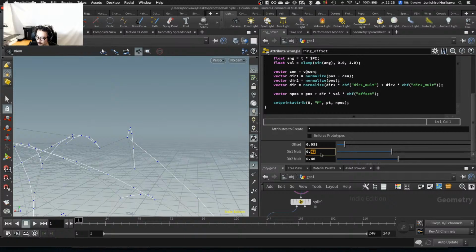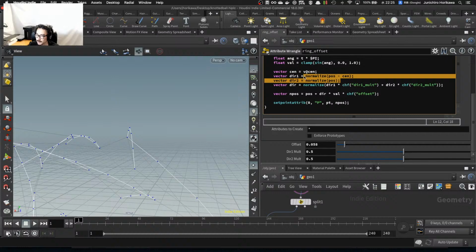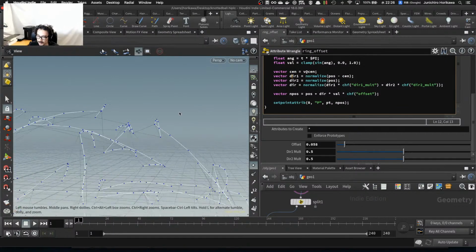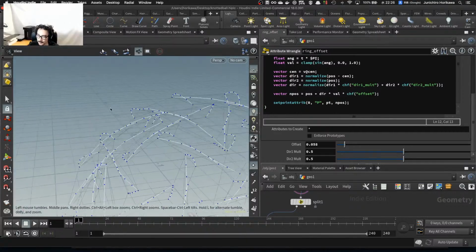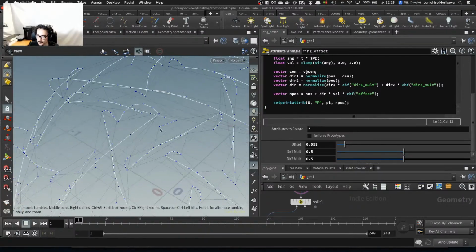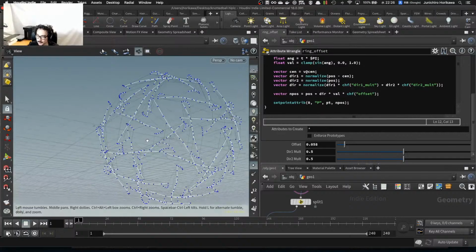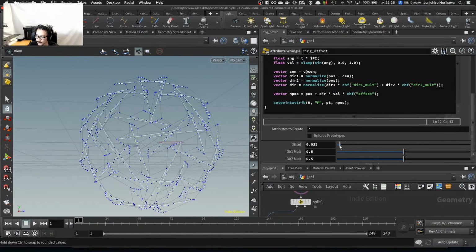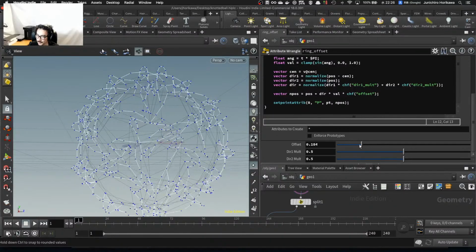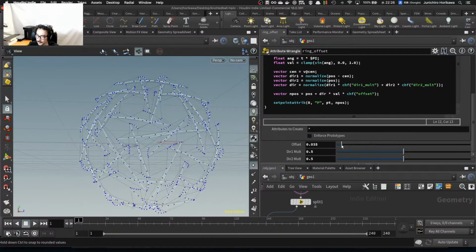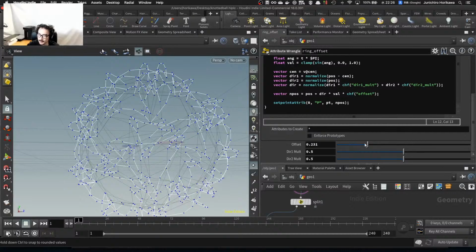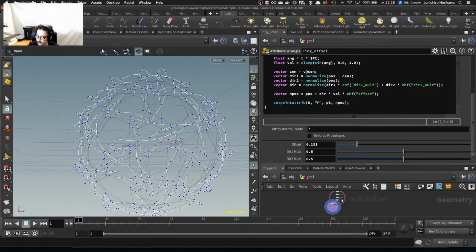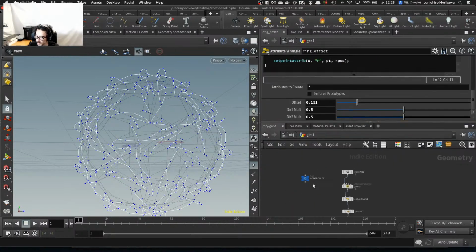Now I'm gonna set it to 0.5 and 0.5, meaning setting the direction 1, direction 2 weight the same, so that it is affected by both directions in the same manner as a default. And I am only going to promote this offset value, which controls the offsetness of this curve, the height of this arch, to this new controller.